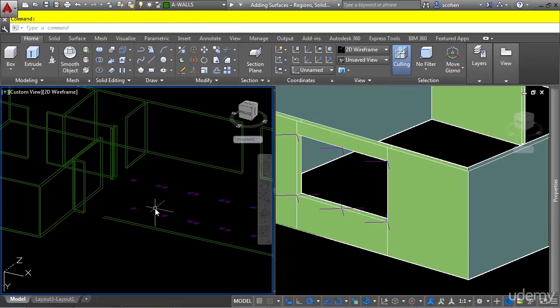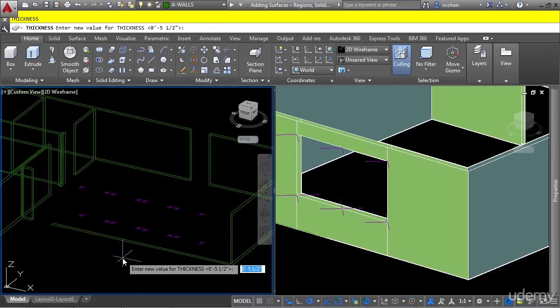This wall has some windows. There are some pre-created points that you're going to use to create the window part. The first thing we're going to do is simply draw a polyline that outlines the wall. So let's go ahead and do that. First, let's change our UCS back to the WCS. We'll change our thickness back to 0 as we don't want to draw a polyline that has a thickness.